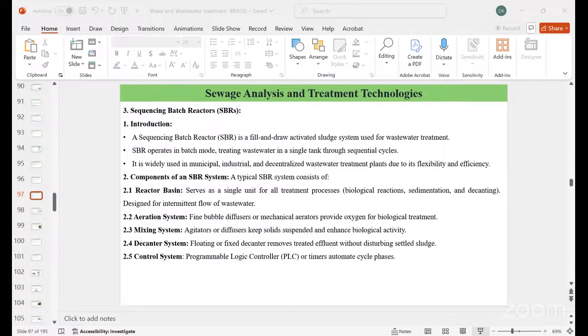And these are used for the oxidation of contaminants by using OH radicals and inorganic ions particularly. Alright, so these reactive species oxidize the organic contaminants and break them down into simpler and less harmful substances, which often leads to complete mineralization, that is conversion to CO2, H2O, and inorganic ions.